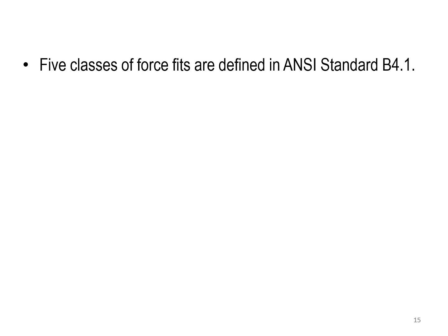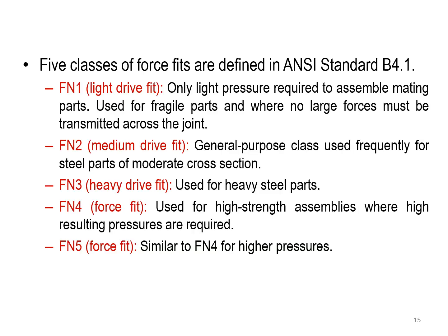Now, the five classes of force fits are defined in the ANSI standard B4.1. The FN1 is for a light drive fit, and the FN2 is for a medium drive fit. The FN3 is for a heavy drive fit, and the FN4 is for a force fit. And finally, the FN5 is similar to the FN4 for higher pressure, used for higher strength assemblies where higher resulting pressures are required.